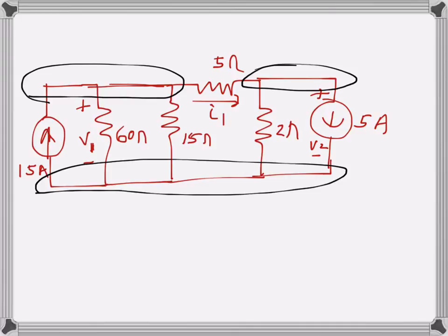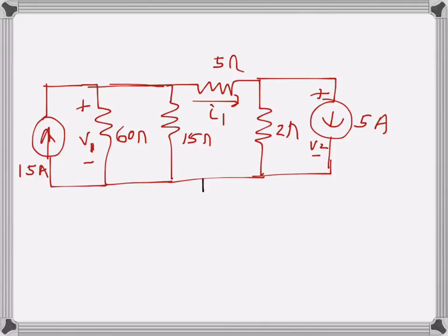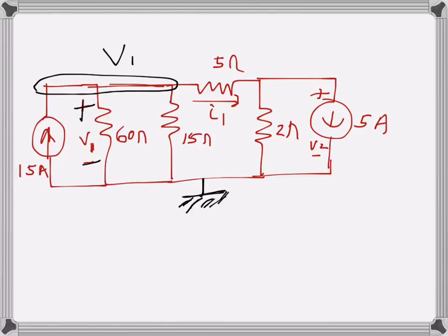Basically here in this case I will assign this node as the ground node, so this one will have 0 volts. This node, let me call this one, we already have the voltage of this one, since the drop here is V1 and this one is 0 volts, so this node's voltage will be V1. Similarly, if we look at this node, since there is this drop V2, the voltage will be V2. Since from 0 here there is a rise of V2, the voltage here will be V2. So we have assigned the unknown node voltages.